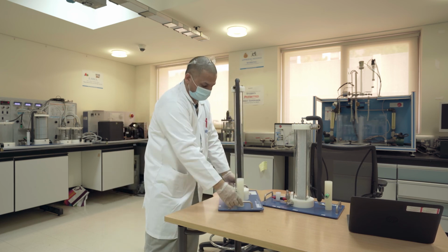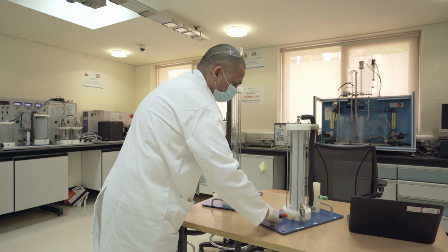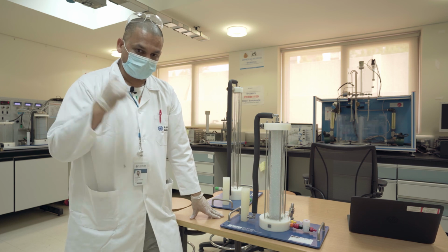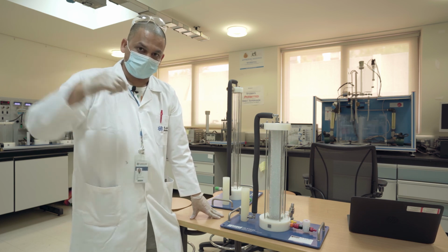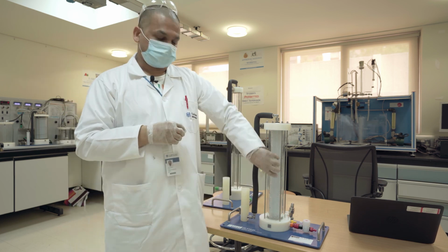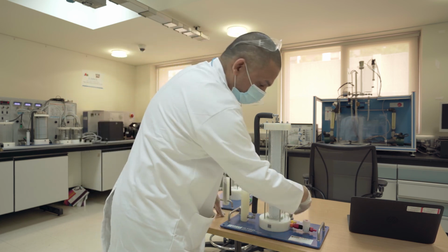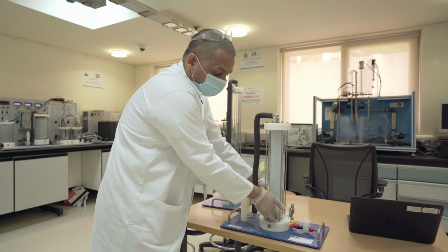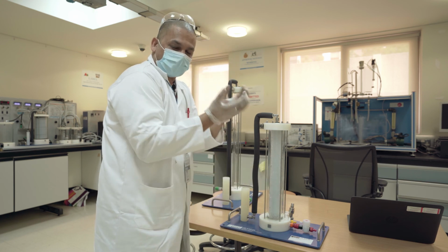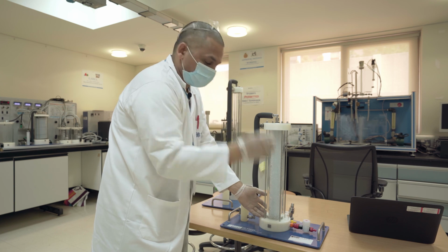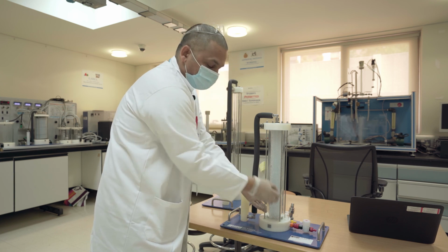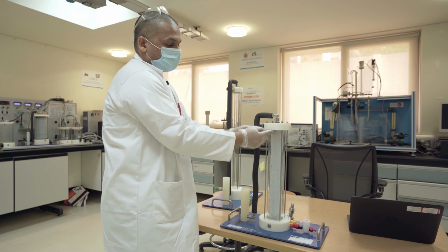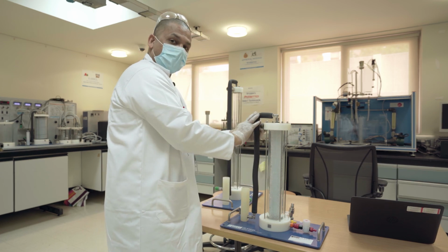Now if you want my plug flow reactor, the plug flow reactors are basically of two types which we have here. The one that we already saw was the pipe or the tube. Here we have packing. Again the same logic applies. You have feed A, feed B, both coming here, coming in contact, and flowing through the void, or the space that is available for flow, and then going up and coming out from here. By the time they come out, they are in equilibrium.